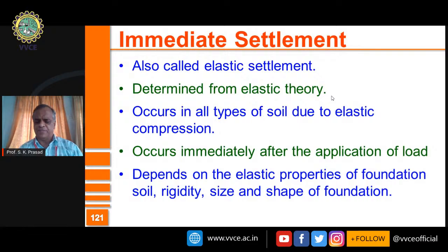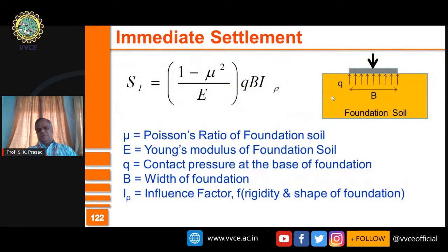Some of them may be stiff, with less elastic immediate settlement. Some of them may be soft. It all depends. So as I said, it occurs immediately after the load is applied, and it depends upon the elastic properties of the foundation soil. It depends on the rigidity, size, and shape of the foundation. So, friends, I want you to remember this formula. Here the bracketed term is the elastic property, (1 minus mu squared) by E.